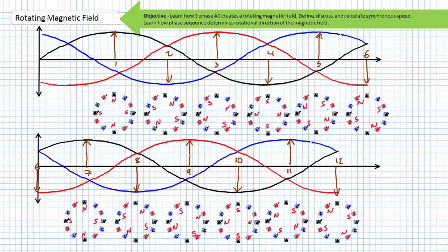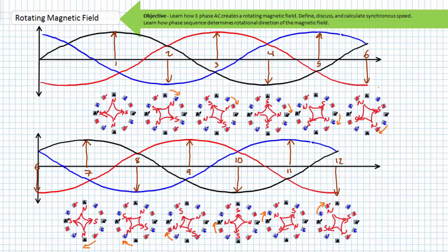When we insert the magnetic quadrupole and these observations are arranged with respect to time, note that the stator magnetic field continually revolves in the clockwise direction. However, at time T6, note it has only completed a half a revolution clockwise. The second cycle of the waveform takes it the rest of the way home. Notice because of the quadrupole arrangement, every pole contributed towards angular displacement of the rotor.